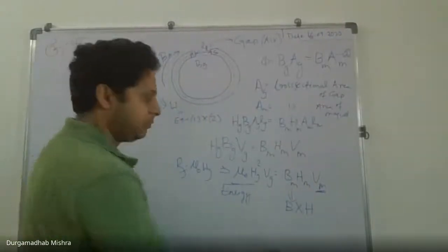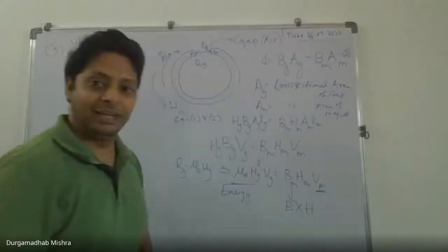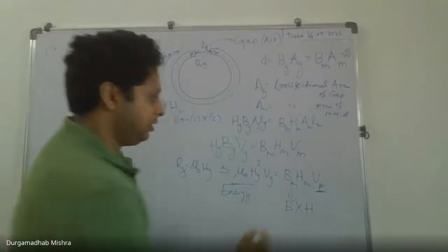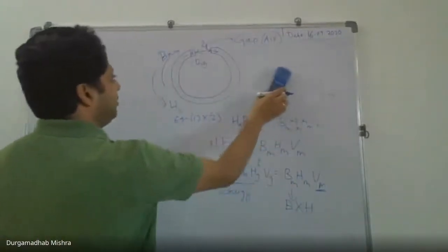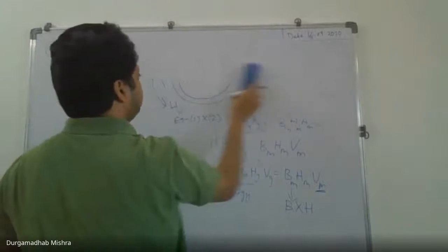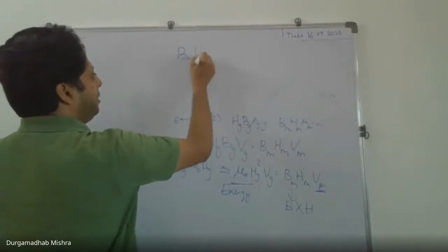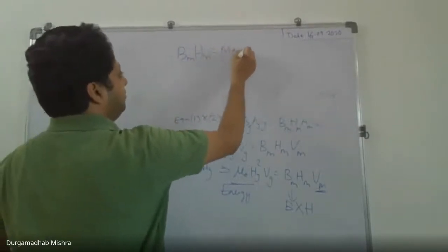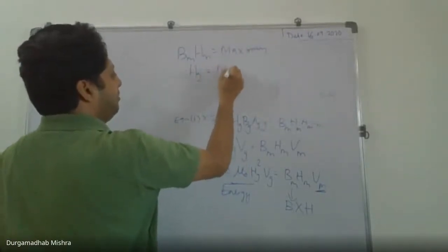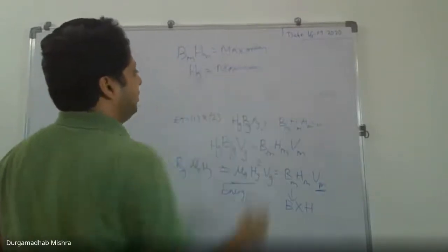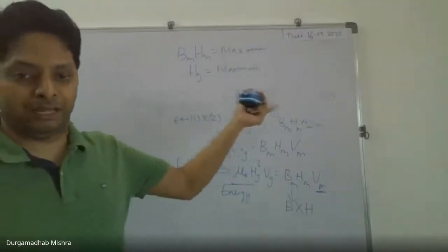So what I have to do is design the magnet in such a way that the product Vm into Hm is maximum, so that Hg is maximum. Our goal is to maximize Hg, because that is the best permanent magnet.